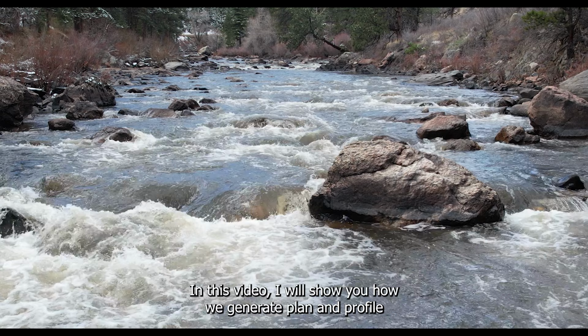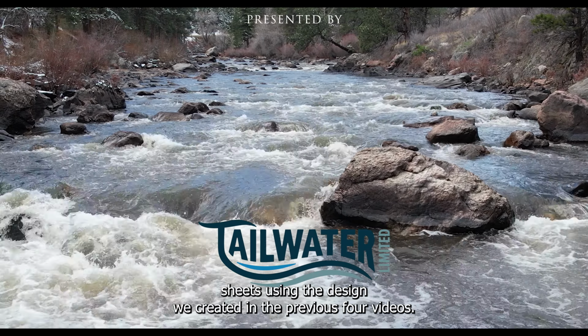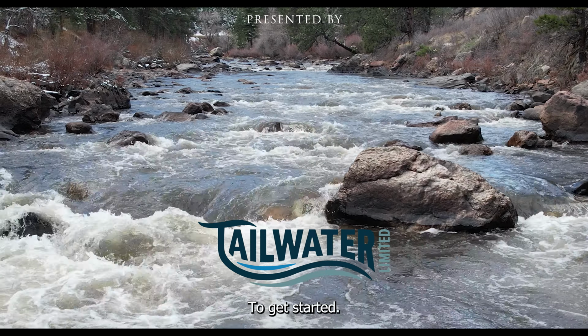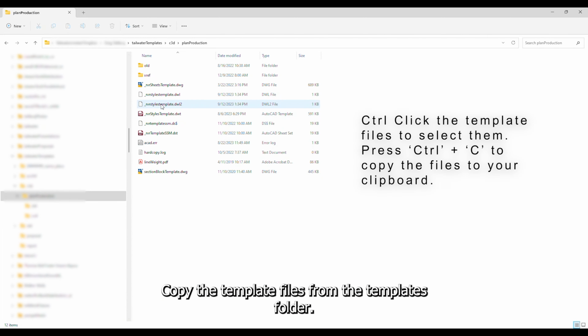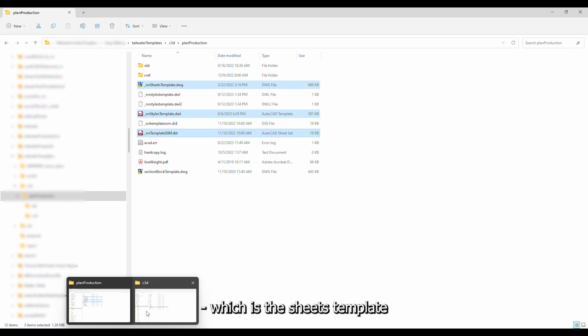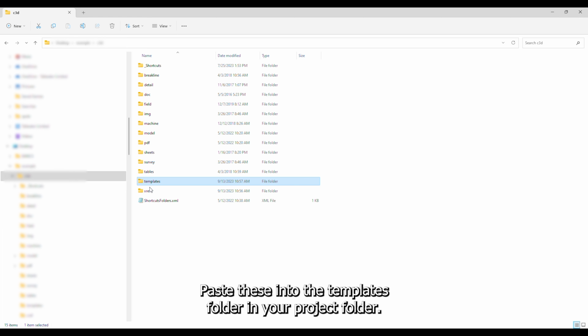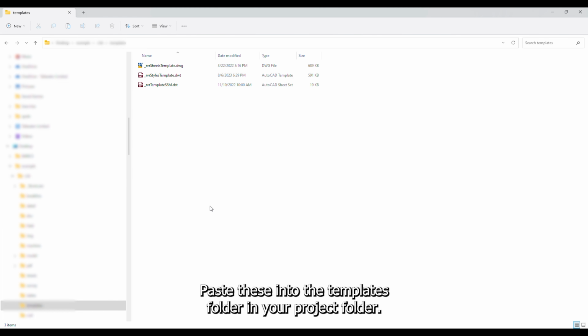In this video, I will show you how we generate plan and profile sheets using the design we created in the previous 4 videos. To get started, copy the template files from the templates folder. We are after the RVR sheets template.dwg, which is the sheets template, RVR styles template.dwt, which is the styles template, and RVR template ssm.dst, which is the sheet set manager template. Paste these into the templates folder in your project folder.